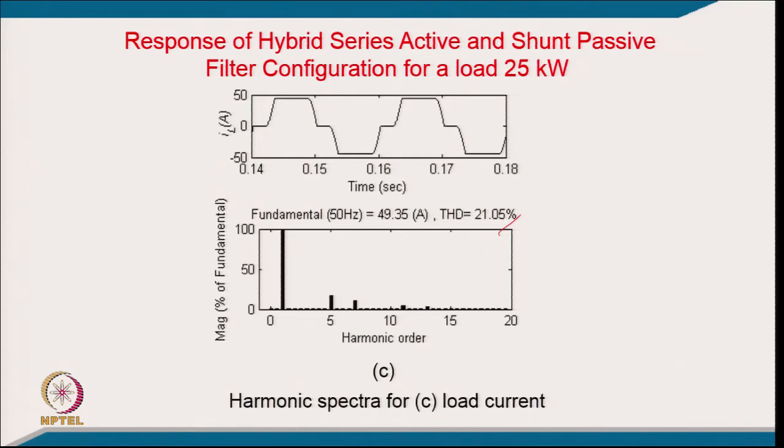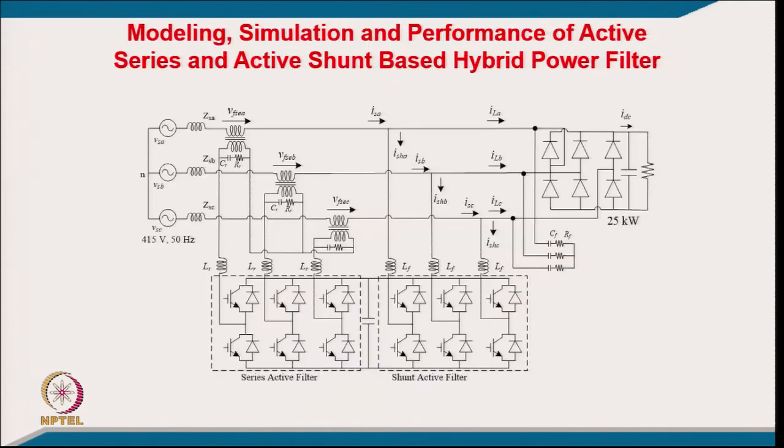So, we are not disturbing the load, the current still remains constant on the DC side, and we are able to improve the power quality on the grid side by maintaining the harmonics to less than even 5%, as well as the reactive power almost negligible on the supply side, by properly designing the passive filter. So, this is another case study where we are using two active filters, a shunt active filter and a series active filter.